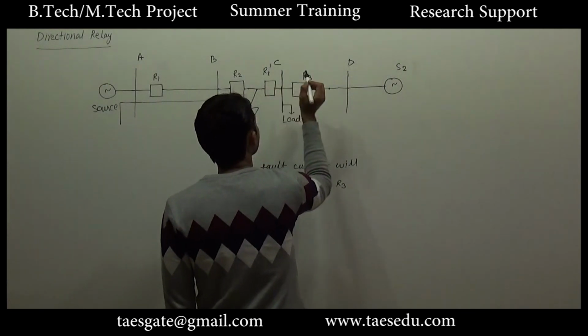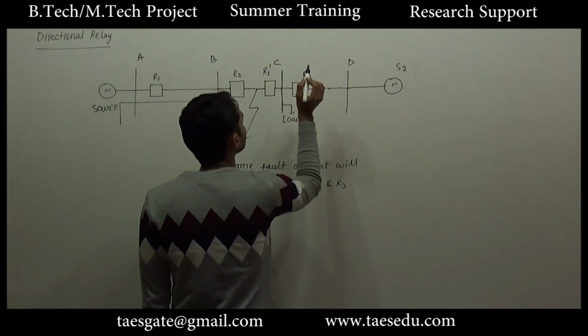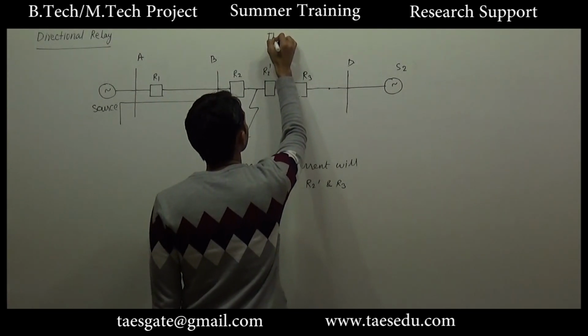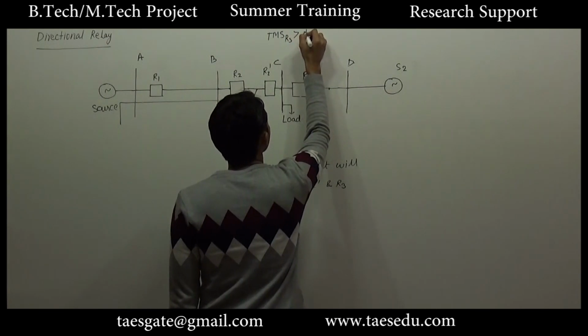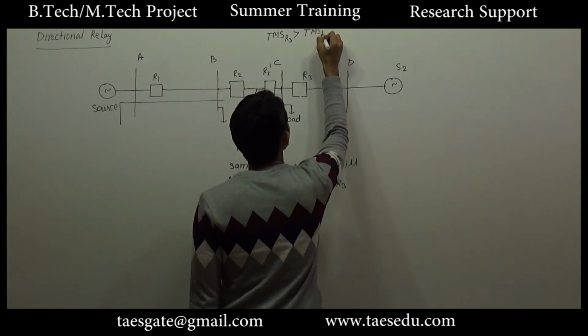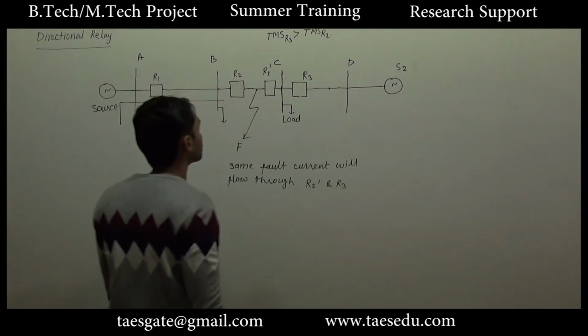for this fault the possible solution may be to set the TMS of R3 greater than TMS of R2.